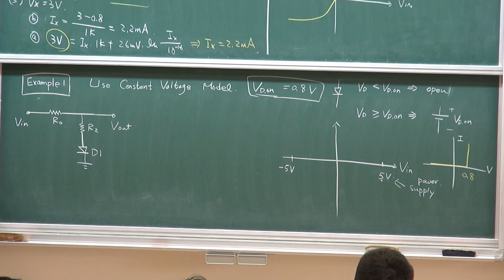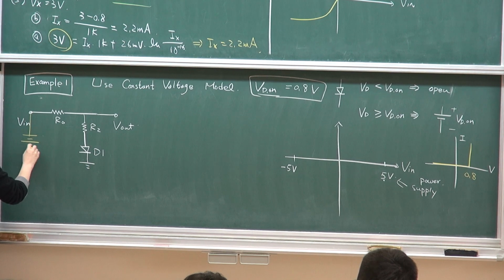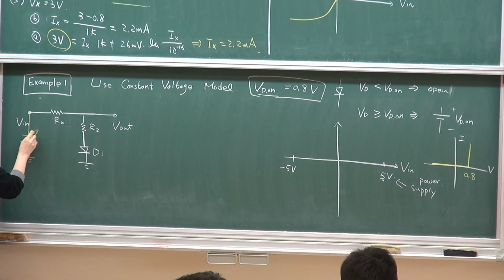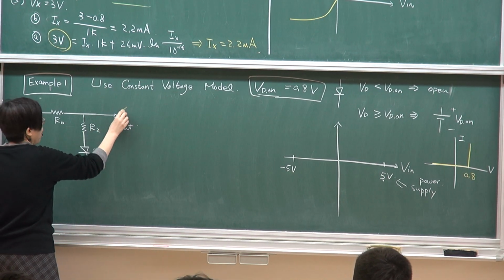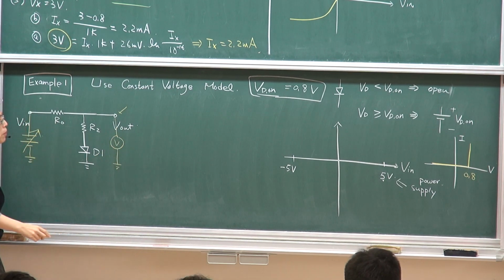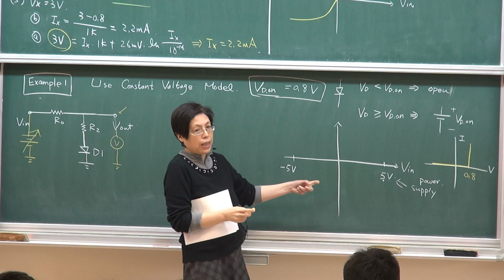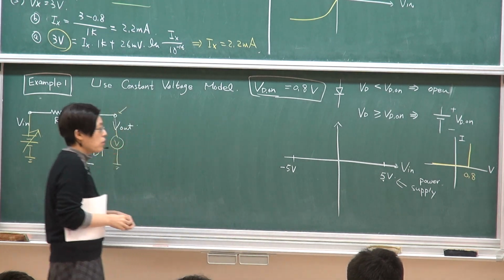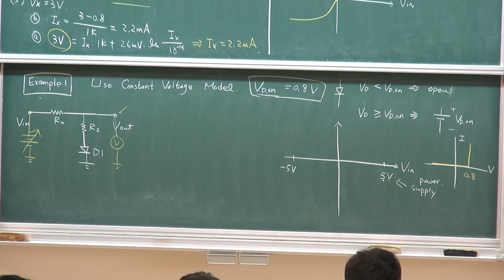If you have a circuit, what you do is simply sweep. You give it a power supply, sweep the input and observe the output. You use a voltmeter to measure the output, and you should be able to get the transfer curve. In this case, we're going to get it through our model.